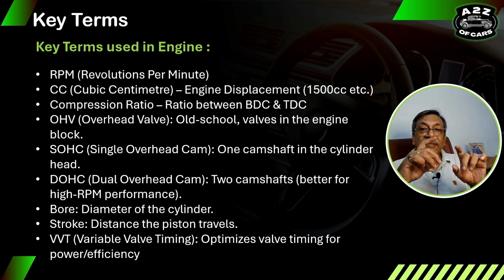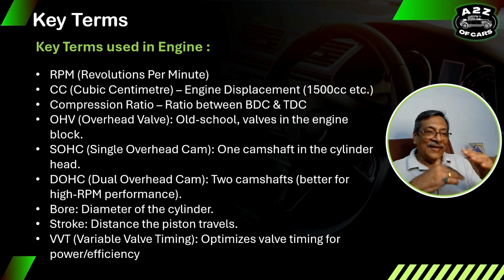But the valve opens and closes because of the movement of the camshaft. The higher the speed, the faster the valves are opening and closing. So the amount of air and fuel mixture required is not going inside the cylinder. That actually reduces the performance of the engine at high speed.